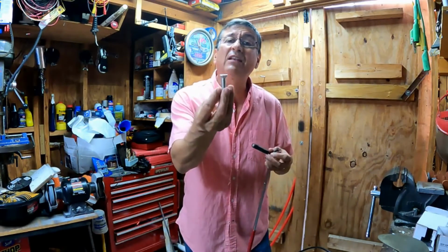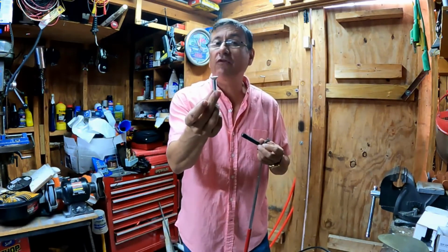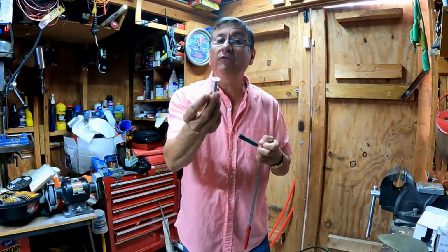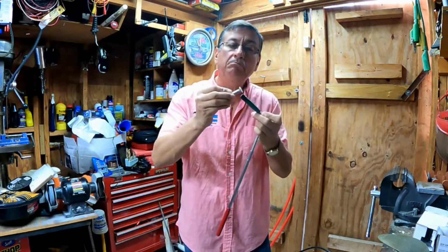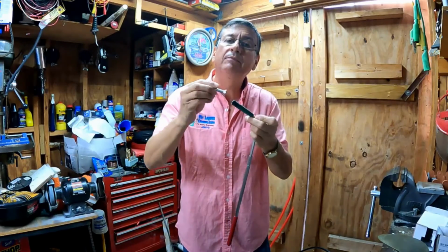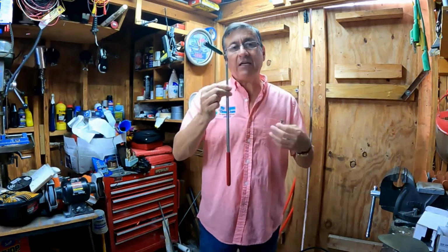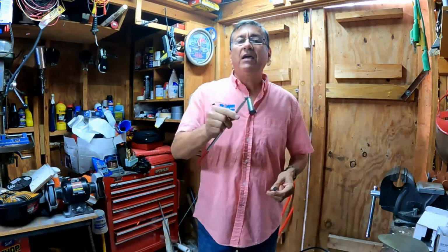This one is a stainless steel with high content of chromium and high content of nickel. This one is not magnetic. One way to verify if the hardware used by subcontractors is appropriate for the marine environment is with the magnet. For that reason, a good engineer has a magnet in the pocket to verify if the hardware used by other contractors is appropriate in your boat.